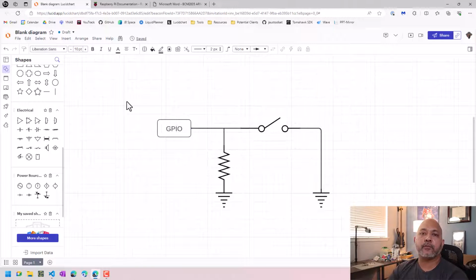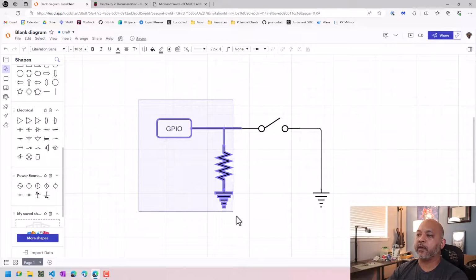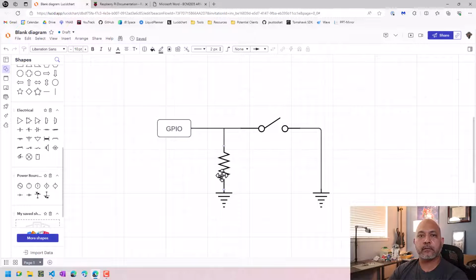Now, what happens if you don't connect the connections correctly? Let's say you configure the GPIO pin to be a pull down pin, but then your wiring into the Raspberry Pi connects the switch to ground. The GPIO pin will be correctly pulled to low, 0 volts, when the switch is open.